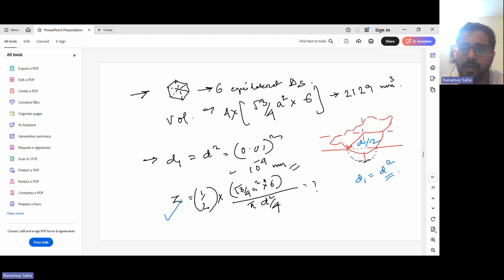So the next question is, in case of ultrasonic machining, if you take the grit diameter to be D, whether it is a perfect sphere. No, it is not a perfect sphere. The grain is never a perfect sphere. So to accommodate that, empirically, it has been concluded that we take the square of whatever diameter we are getting.